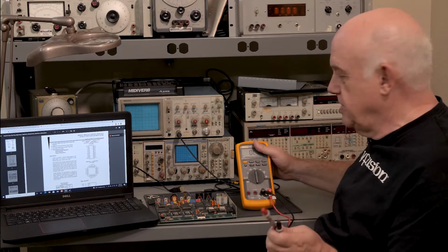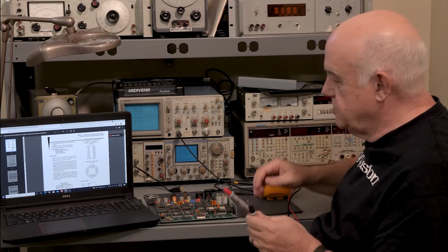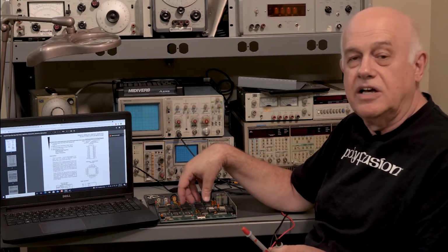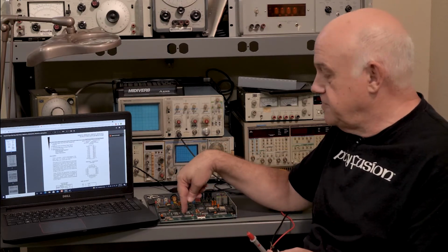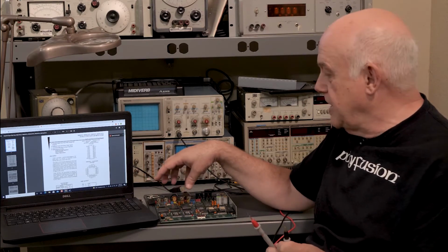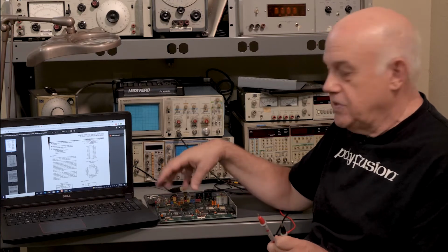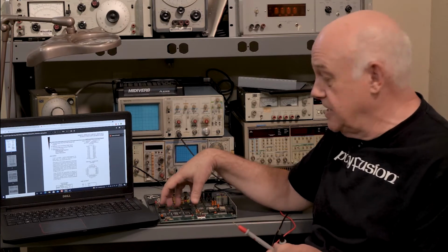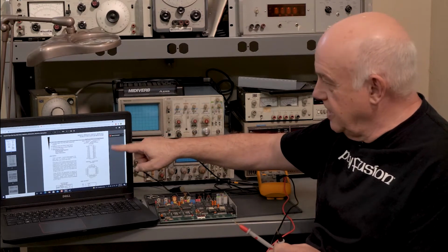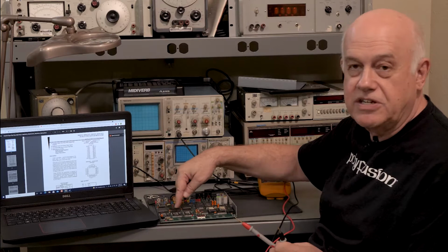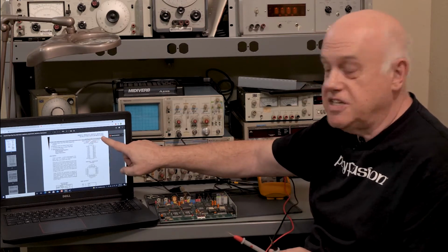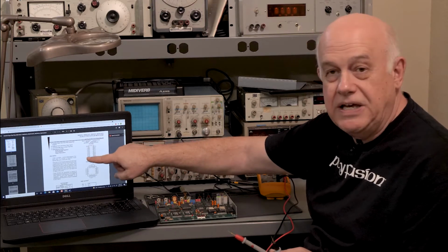So how are we going to do that? Well, what we're going to do is first we're going to study the chips that are on here. Now we have an advantage that the chips here are clearly marked. They're not erased, they're not rubbed off with sandpaper, they're not labeled funny, they're not encased in epoxy. They're right there for the world to see, which means we can go on the internet and pull a data sheet for every single part. So that tells us 2 things: what the part's function is and what each individual pin is.